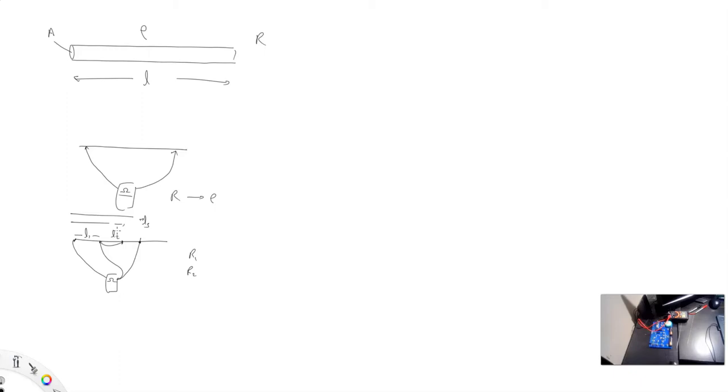So here's a suggestion. This is the circuit we're going to build, right? We take a battery, connect this conductor over here, we can put an ammeter here, measure the current in the circuit, and we take the voltmeter, place one end over here, and I can place, let's say, the other end over here.